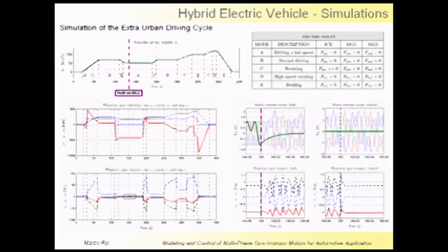But the dynamics of the vehicle should be unaffected with respect to the fault because the motor can continue to work with the remaining phases. This ripple can cause some mechanical failure, so it is necessary to modify the control. When the fault-tolerant control proposed during my research activity is applied, the torque ripple disappears, so the motor can continue